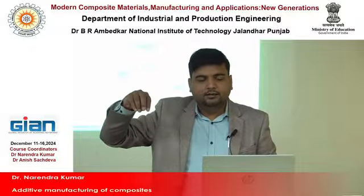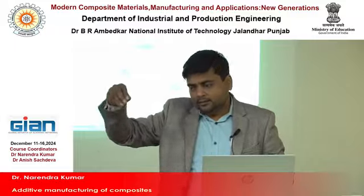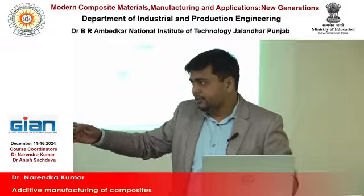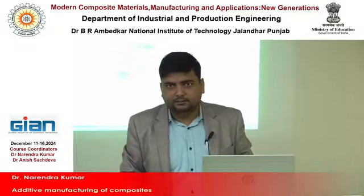Then the platform is lowered by the layer thickness, and again powder particles are added with the help of a recoater arm, and the same process is repeated until the whole part fabrication is completed.